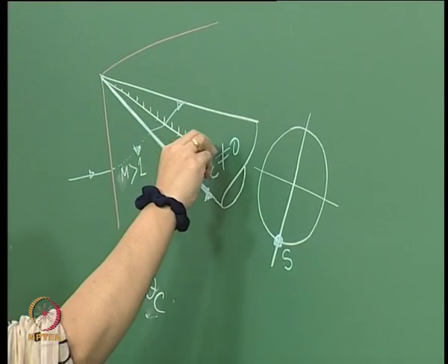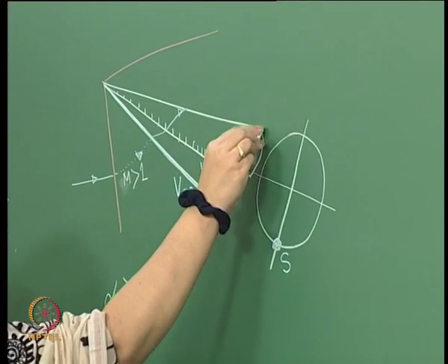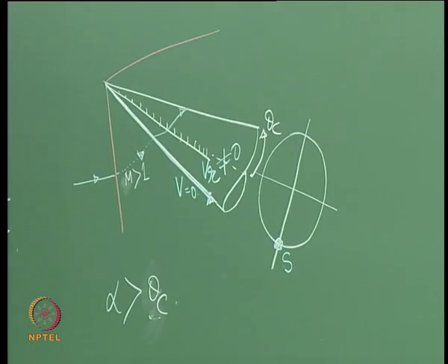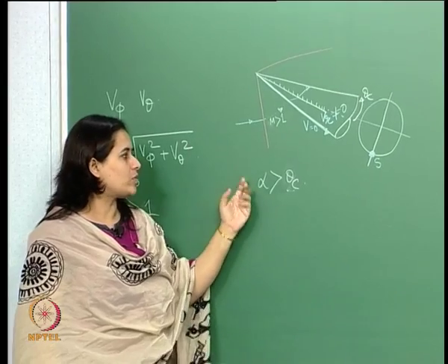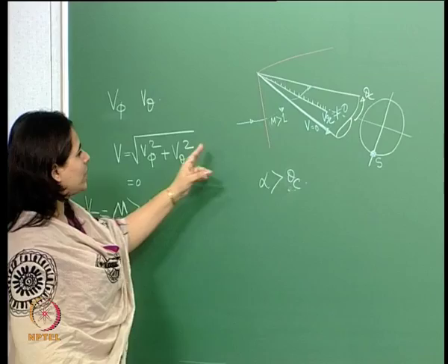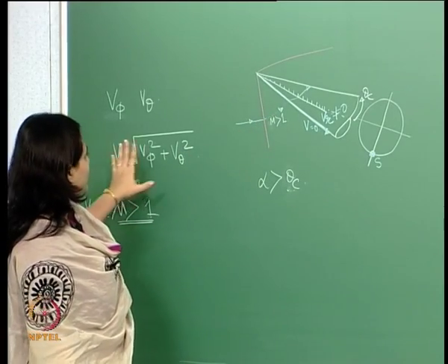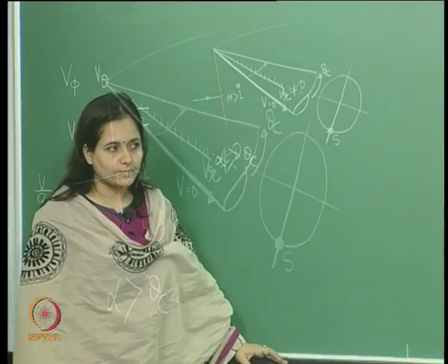Yeah, actually, well, I kind of drew it here. So this is my theta c. Half cone angle is your theta c. So this embedded shock thing will happen most of the times for a very high angle of attack. A very high angle of attack will end up increasing this velocity, and if this becomes supersonic, we have these embedded shocks.